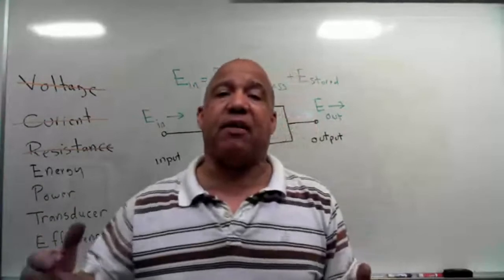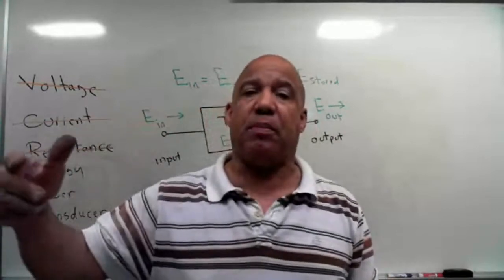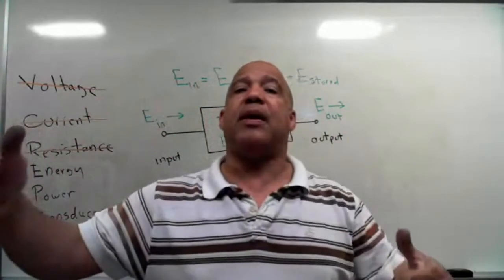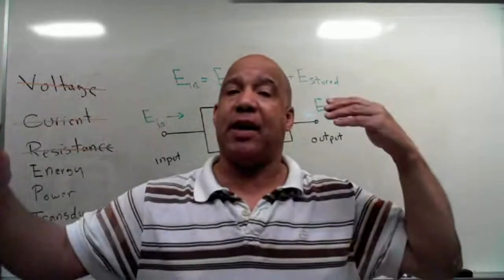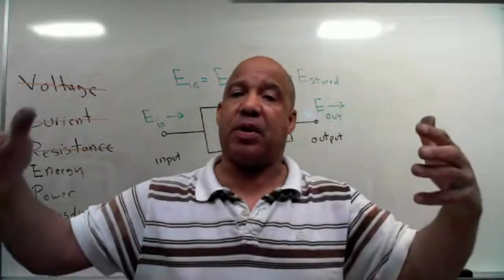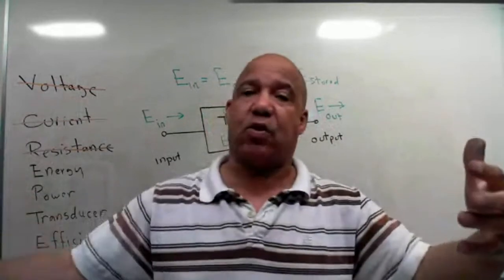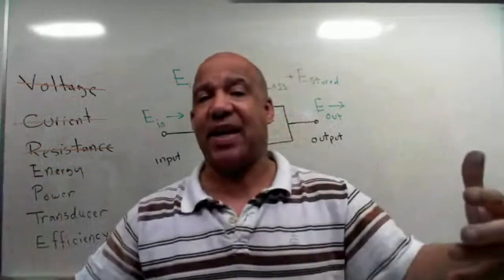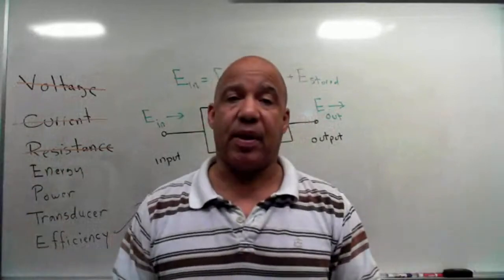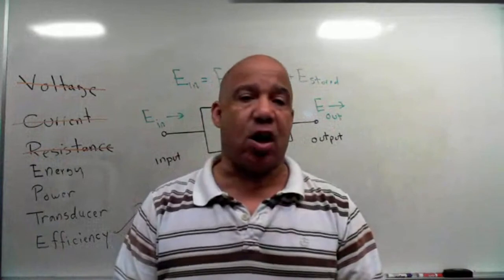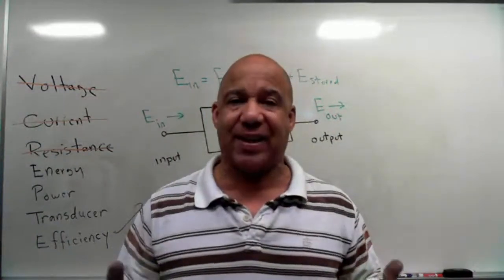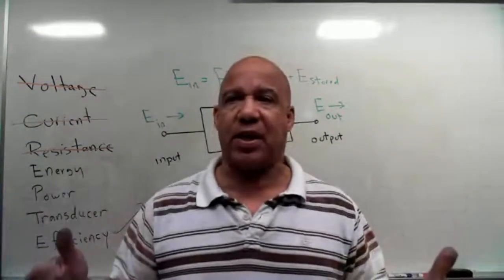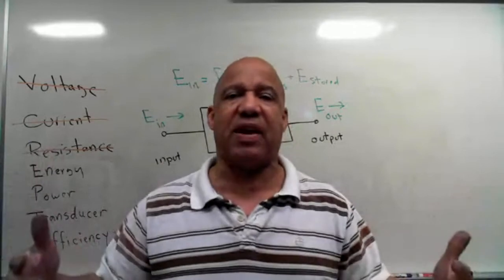You also notice that the 60-watt fluorescent bulb burns brighter than a 60-watt incandescent bulb, because with the fluorescent, more of the energy is going into light, and with the incandescent, more of that energy is going into heat. Really, wattage is a terrible way to talk about brightness because you don't know the efficiency of the device.